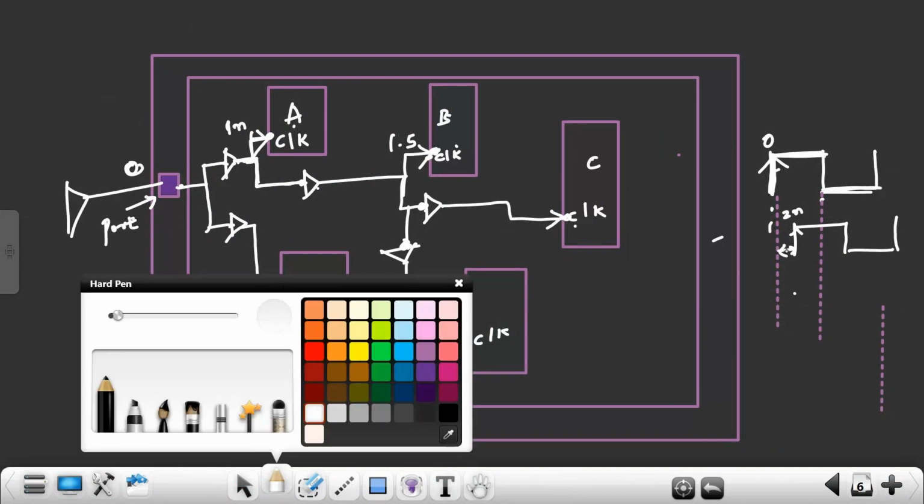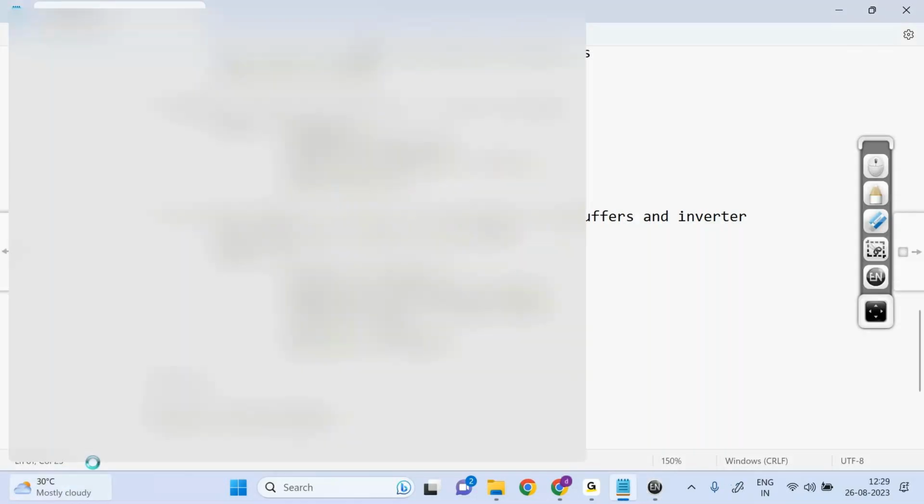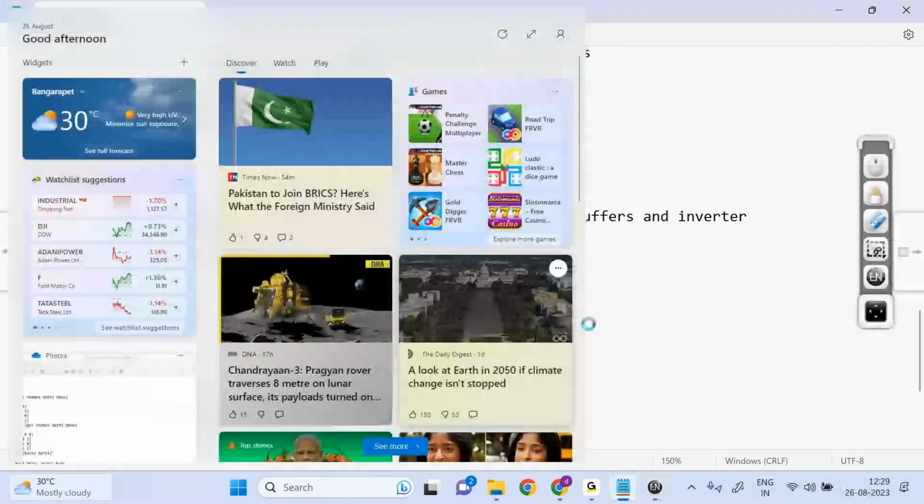See, the actual clock has a rise time and a fall time. Like this is the actual clock. This is called minimum on time. This is called minimum off time. Whether the clock reaching every flip-flop has minimum off time or minimum on time or not, that we will check. That is called the pulse width check. So these are all the different checks we'll do.